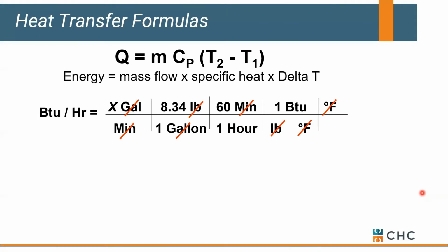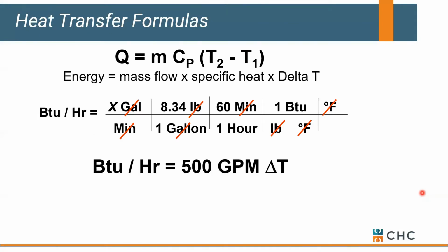If you remember from our boiler class, we talked about BTUs into the system is equal to a constant of 500 times gallons a minute times delta T. And again, if you wondered where 500 comes from as a constant, it's simply the weight of water times 60. It gets our units to work themselves out and becomes a constant. If we're dealing with glycol, that number changes a little bit. It might drop to 490, it might raise to 510. Depends on the viscosity or specific gravity of glycol, but for the most part, this is a constant.